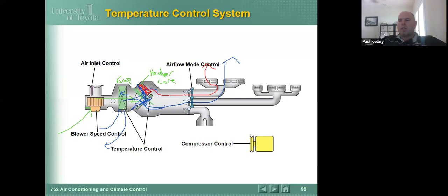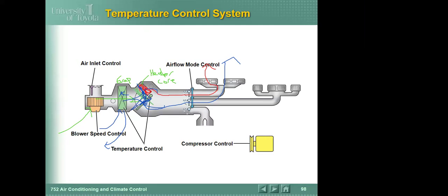If a TXV is malfunctioning, we could diagnose that. In the typical way a TXV would malfunction, there's a couple. One, the TXV has a small passage, right? So if we end up with some debris in the system, where does the debris most likely get stuck? What do you think? It's going to be the smallest point in the system. So where do you think it's going to get stuck? Inside the TXV valve. Exactly.